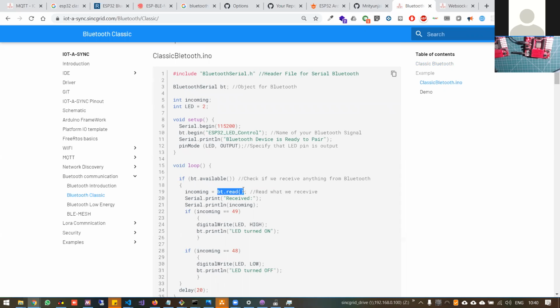I will also explain how Android phone or Android software development can be used for sending and receiving data over a serial connection. You can take it as something like the serial or RS-232 connection that we use in embedded systems, and this is more or less exactly the same profile. It has some baud rate. There are certain baud rates specified by different manufacturers. For example, Microsoft has 57600 for certain kinds of devices. They have the set baud rate, and those kinds of libraries are provided.